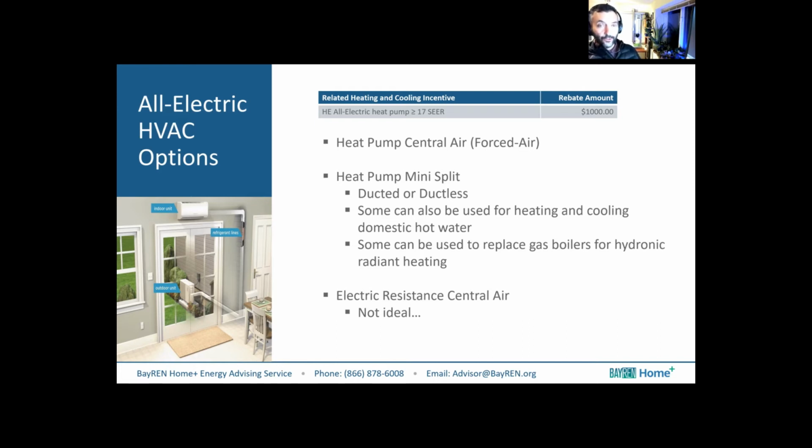So if you've got a 2,000, 3,000 square foot house, and in California, we find homes with like 2 to 3 HVAC systems, which is totally overkill and ridiculous. They can install something like a mini split. They can use multiple emitters, which can be cassettes in the ceiling. They can be like this image on the left here, indoor unit. That's a wall mini split. It has a line set with refrigerant, power, and drip that goes out to the outdoor unit.